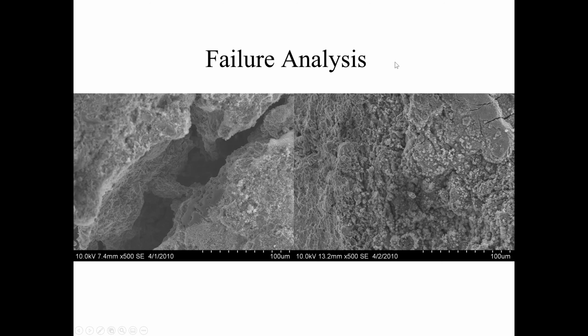You can do failure analysis of metals. This is a piece of steel that structurally failed. This is hydrogen embrittlement. It's a secondary electron image. You can see all the surface defects. You can see the grain boundaries. You can see the depth of field is pretty amazing on it. To the naked eye, the steel seems to be perfectly fine.